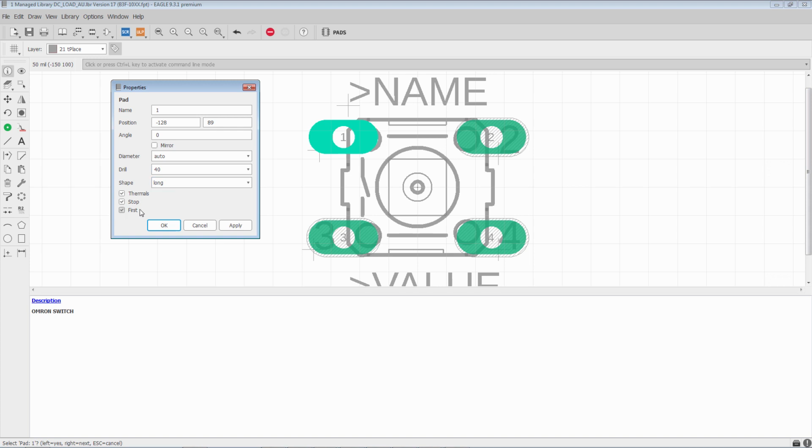So that's one option. Most users that want to somehow distinguish on a through hole part, what they'll do is they'll either draw it on the silk screen, or they'll very explicitly change the shape here in the library. That way it can't be tampered with by the design rules. So those are all ways to achieve the same thing, and that's an option that users have when working with through hole pads. So this covers all of the properties of through hole pads.